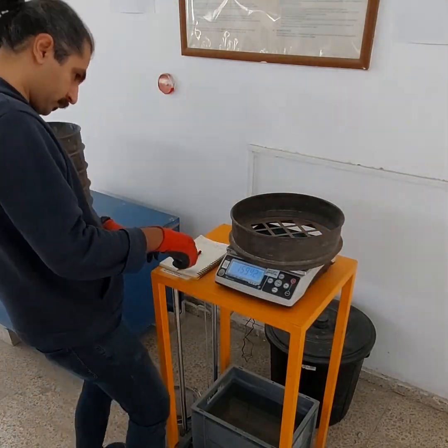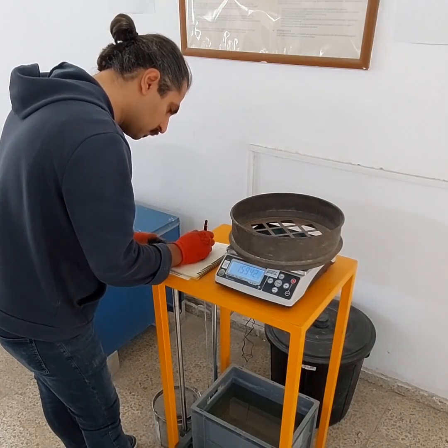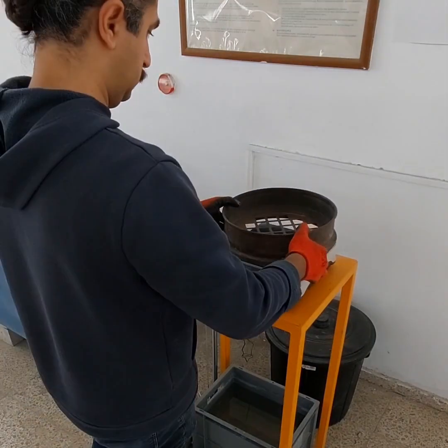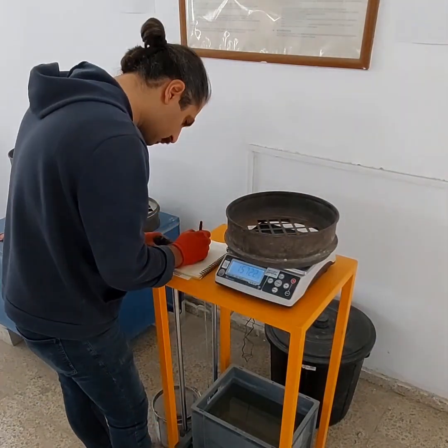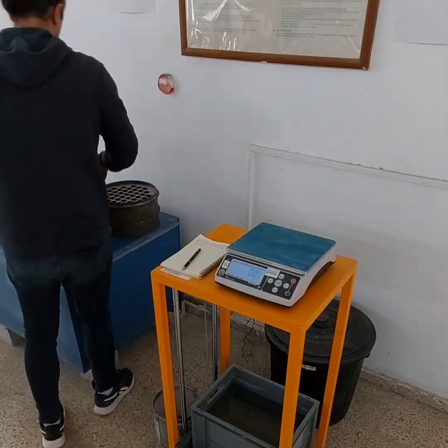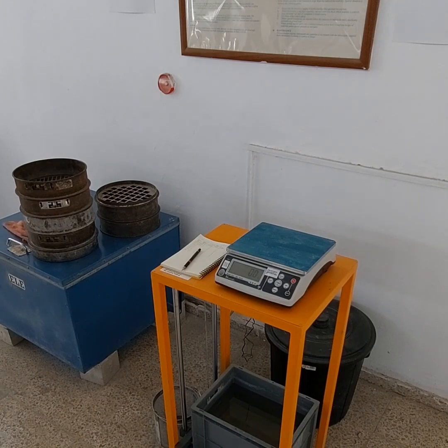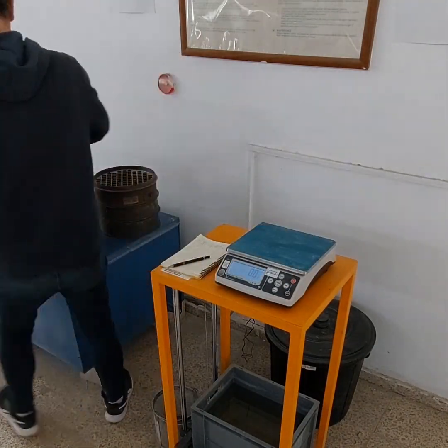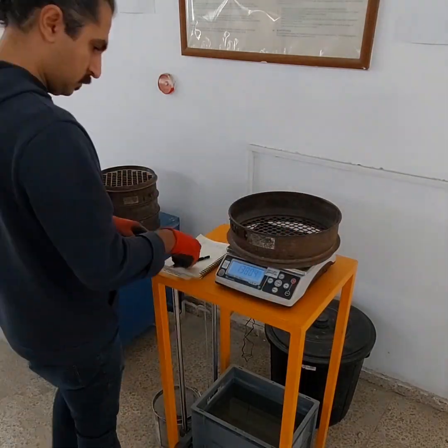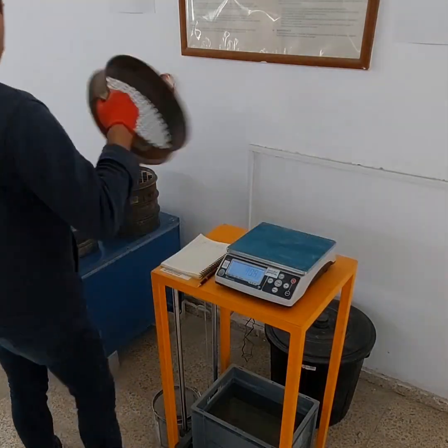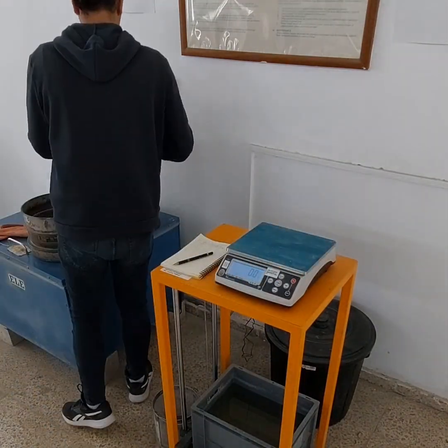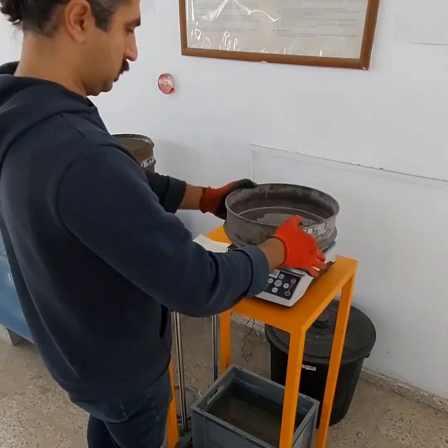To start with the sieve analysis, it's important to first prepare the required sieves as per the guidelines of ASTM C33. This involves obtaining a set of sieves with different mesh sizes suitable for the range of particle sizes in your coarse aggregate. In this case, we will need sieves with sizes of 25, 19, 12.5, 9.5, 4.75, and 2.36 millimeters. After obtaining the sieves, it's time to weigh each one separately and take note of their individual weights.